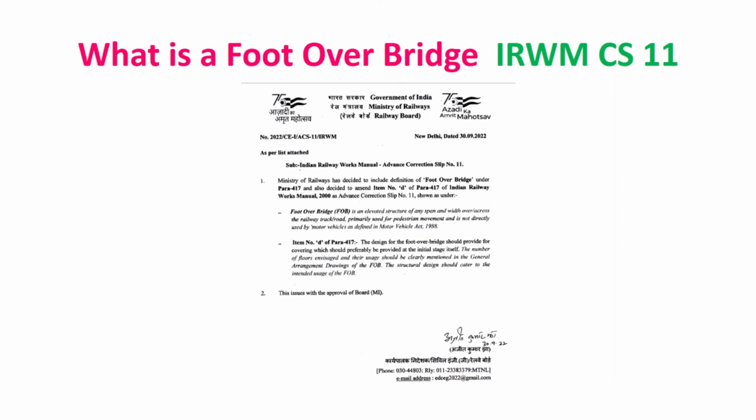Or it may have two transformers in the same complex. Then for one transformer, the clearance from the end is 1.25 meters, and between the two transformers it is X. Again, they have given a certain clause you have to refer to as to what distance I should keep between the two transformers. It may not be required immediately, but sometimes these provisions may be helpful to you.